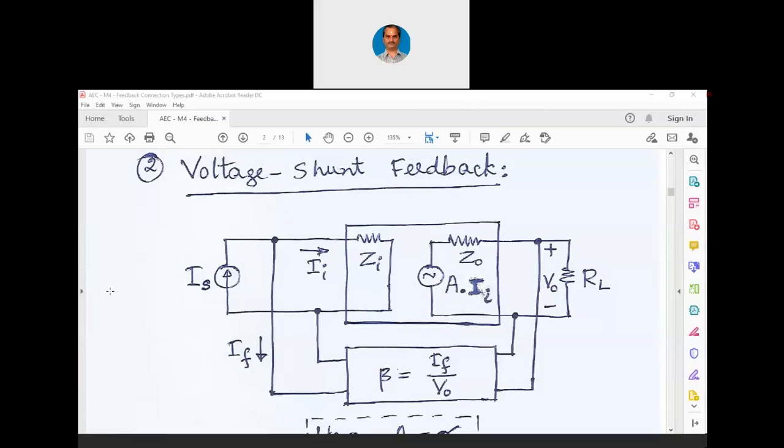You already know that we have 4 types of amplifiers, namely voltage to voltage, current to current, then current to voltage, voltage to current. There can be 4 types. If voltage itself is amplified, it is called a voltage amplifier. If current itself is amplified, it is called a current amplifier, also called a buffer. Now, if the input is current and the output is voltage, we need such amplifiers also in some applications, where at the input side there can be a current which we want to be converted into voltage at the output. Then we can also call it a transresistance amplifier.